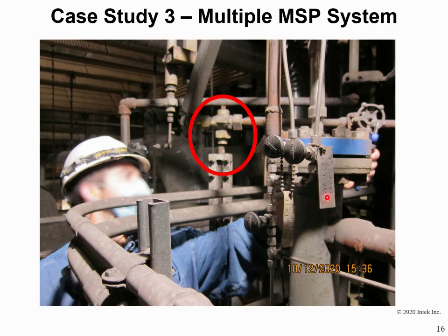The leak that was found was a sheared off pipe stub connected to a sight gauge on a feed water heater. This was not located in a well-traveled part of the plant and would not be noticeable without climbing a ladder to this specific platform. Plant personnel closed the valves around the sight gauge, and the air and leakage immediately decreased to approximately 9 SCFM.